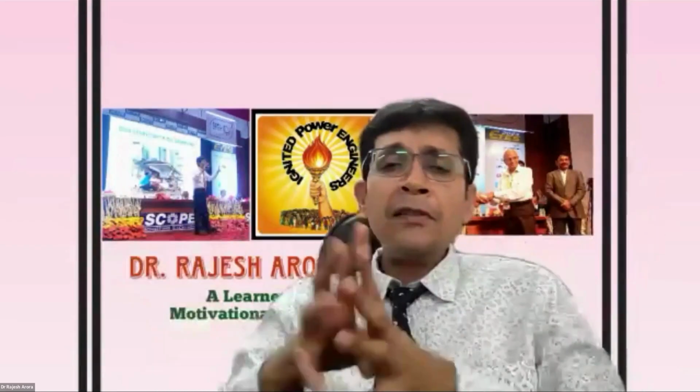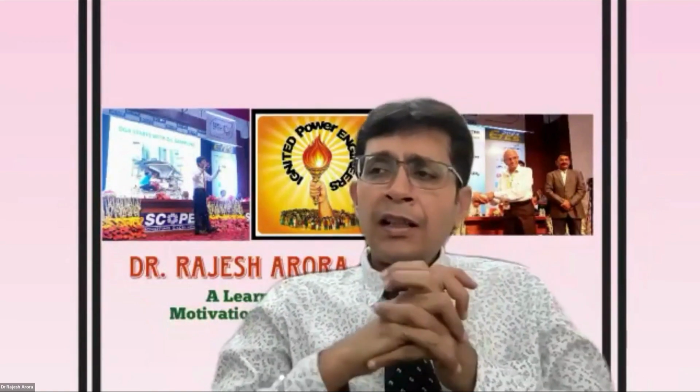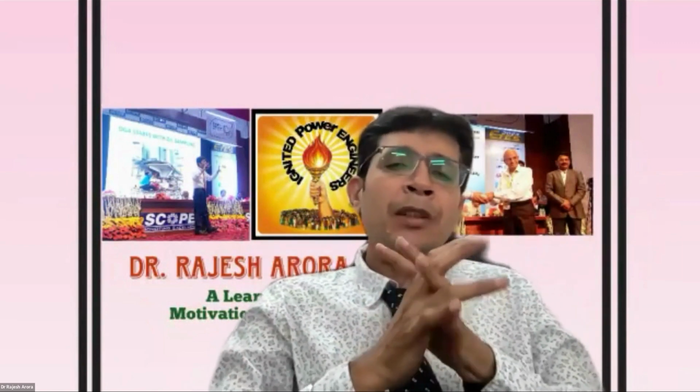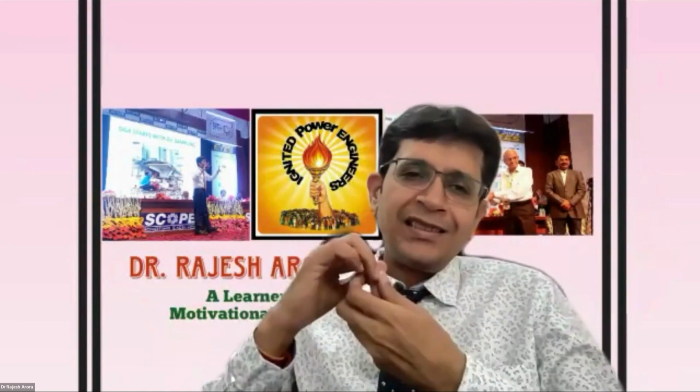Does any expert want to add something, sir? Can you add Dr. Rajesh Arora or other members? I think there is a very good table given in the CIGRE 349 guideline, and they have given the classification of transformers: class 1, class 2, class 3, class 4. That is good, fair, probably wet or wet, based on the relative saturation, the ppm in oil. You can use that, it will give you a fair idea.